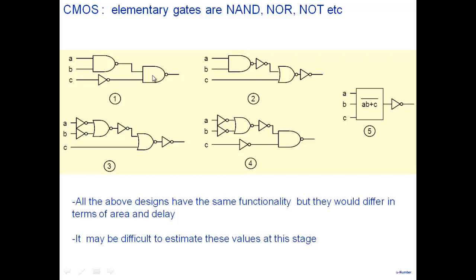It's not. Why? Because of the wires, interconnects, right, between two gates. The wires have capacitances associated with them. When you have to charge and discharge the capacitances, that also causes a delay. You have no idea about what is the length of the wire connecting between here and here. This is just a diagram on paper, right? How long you can make this wire, as long as you want, right? As you have no idea about the interconnect, right?